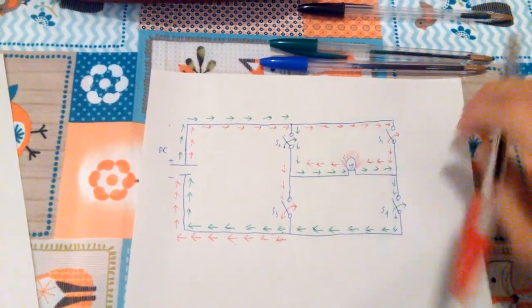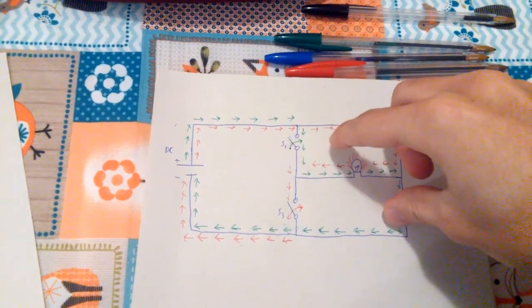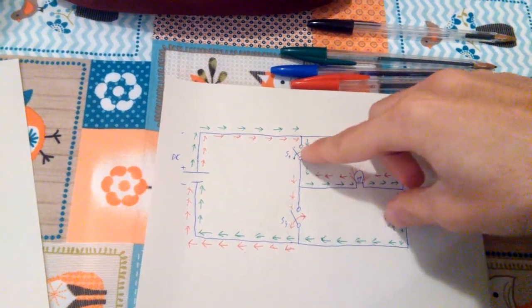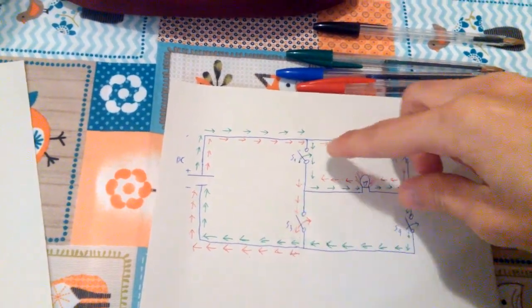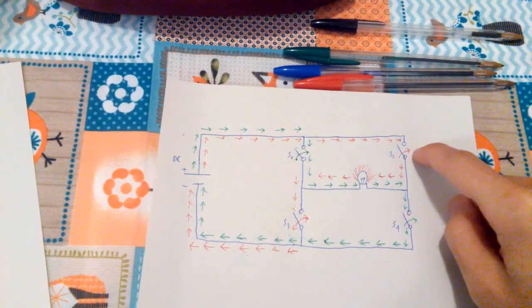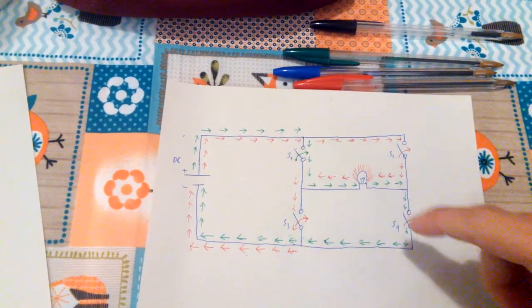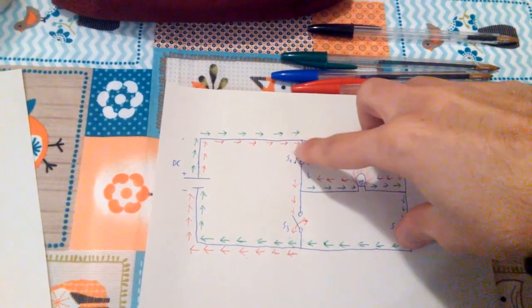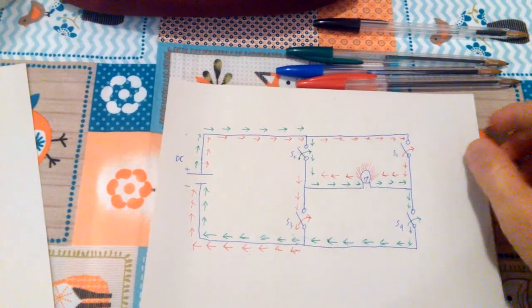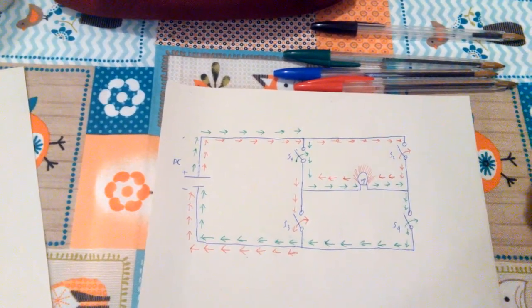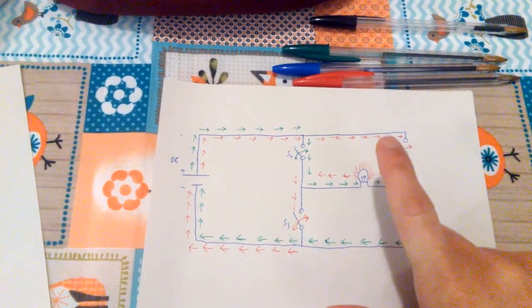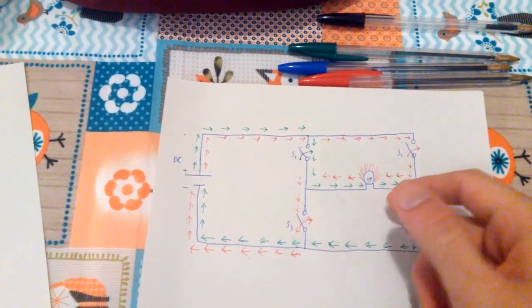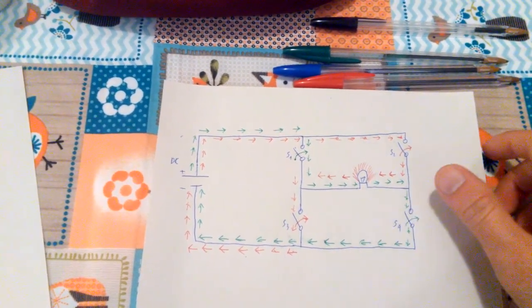So the idea is to basically get those two, close them, and then open them, and then close them, and then open them. As I close them, those two are open. As I open those two, those are closed. So S1, S4 close, S2 and S3 are open. S1 and S4 open, S2 and S3 are closed. And if I do this for 50 or 60 times per second, then my light bulb is going to experience a current flowing in this direction and in this direction and in this direction and in this direction, which is very similar to an AC